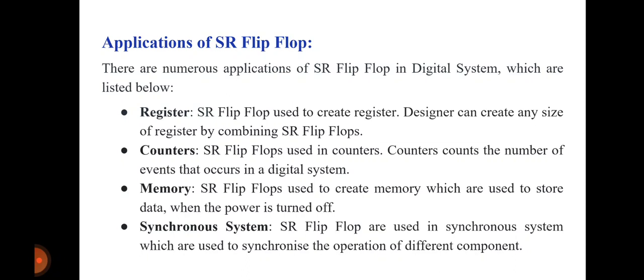Designers can create any size of register by combining SR flip-flops. Registers are formed by a group of flip-flops. Counters: SR flip-flops are used in counters. Counters count the number of events that occur in the digital system, such as the number of clock pulses.